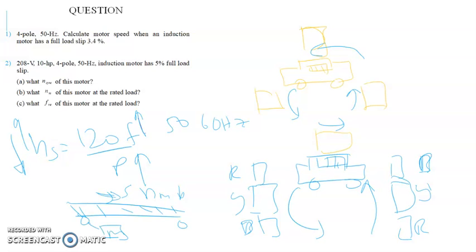Usually in your factory they have what's called a ratio gearbox. You have a high rotational speed here, and before it enters the roller, you have a gearbox. So we have a mechanical gearbox. The gearbox will have a turn ratio of 1/100, which means that you have 1000 RPM here, so only 10 RPM on the conveyor side.